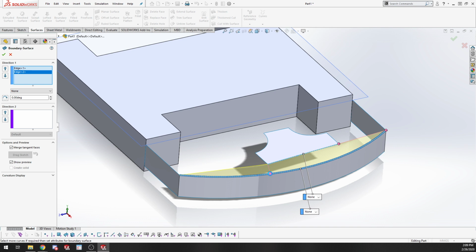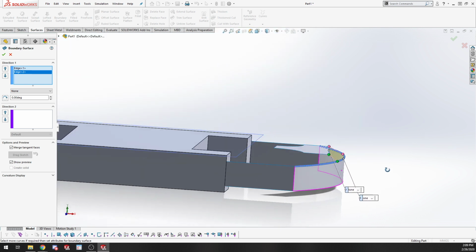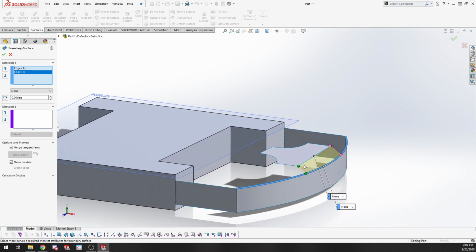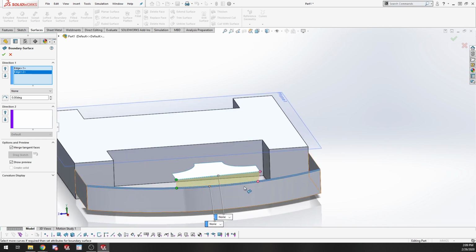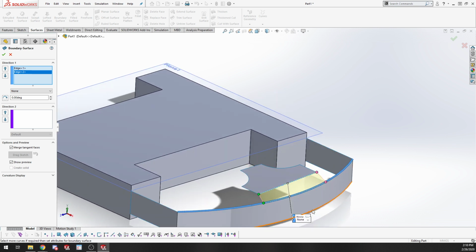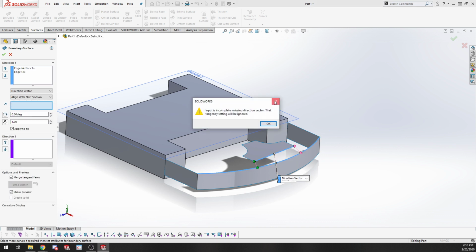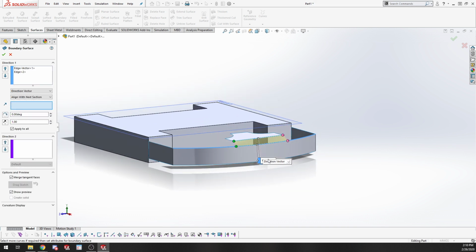One of the things that's a good idea to do with surfacing is to start small. Underdefine your surfaces, so just start in a small section and then work your way out to the larger part. Usually for even more control, I could split up this outside surface into several subsurfaces, so that I know where those points are. But just for the sake of demonstration here, we'll just draw it out to there. All right, and now I just have to move these out of the way so I can see them individually.